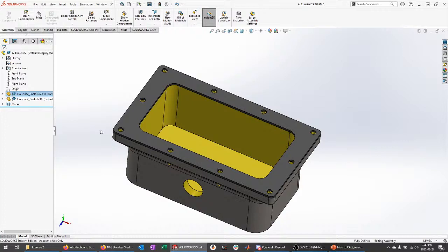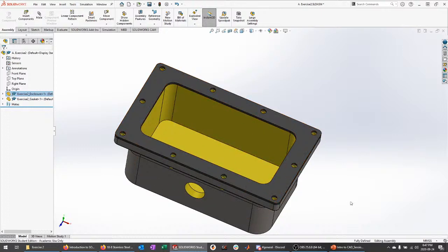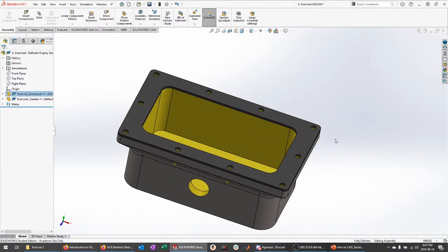On the other hand, if you know you're going to be making changes to this hole pattern, say this is currently, what is this, 10 holes? Let's say I know I might change it to 8, and I don't want to worry about breaking links in the assembly. Maybe I'll constrain it based on the planes, and that'll bypass that issue. So again, advantages and disadvantages, and it depends what your priorities are. For now, to keep things simple, we're just going to constrain off of the holes.